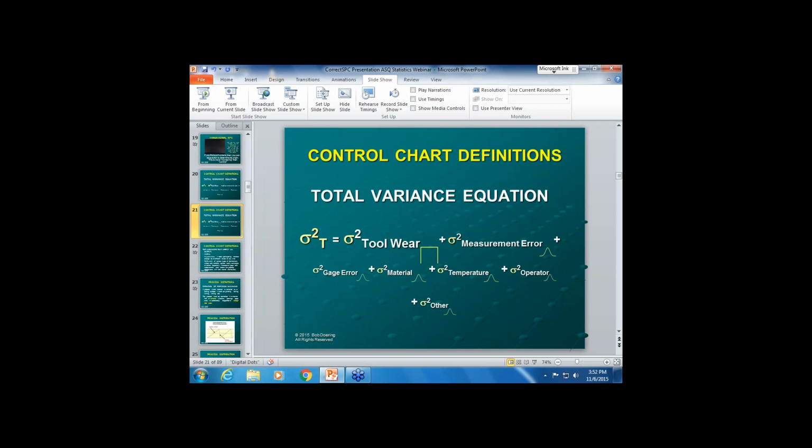Let me tell you something that's interesting about those distributions. If you have a form factor, let's say you're looking specifically at surface finish, the better your surface finish, the closer it is to zero. The further away it is, the more normal it's going to be. So if you stink, it's going to be way out somewhere, you can be normal, and you can use a regular X bar and R chart.